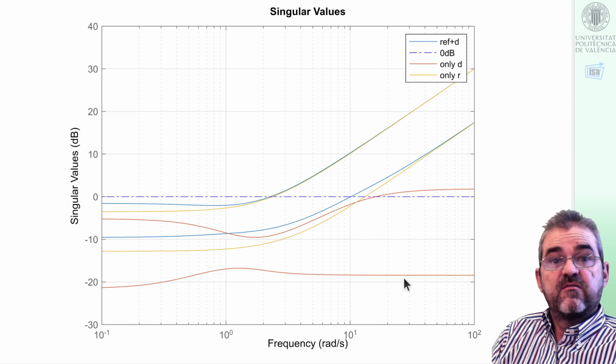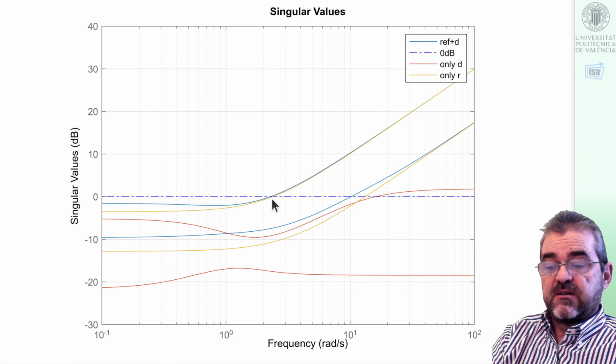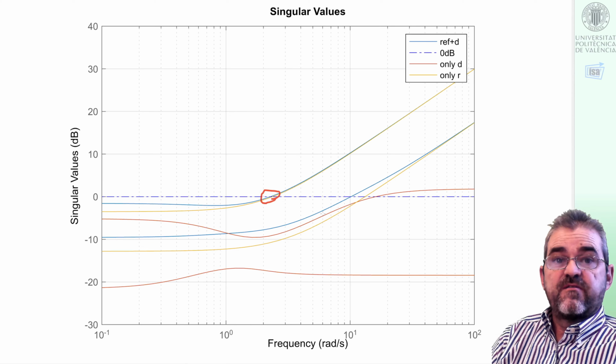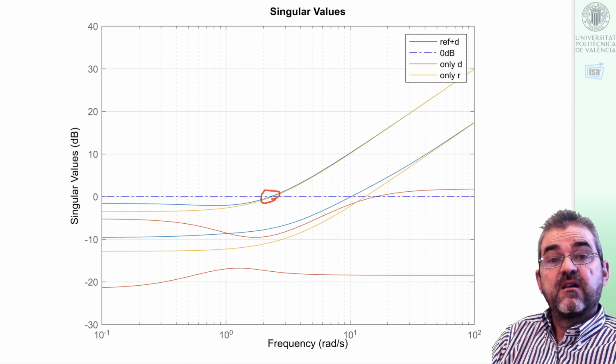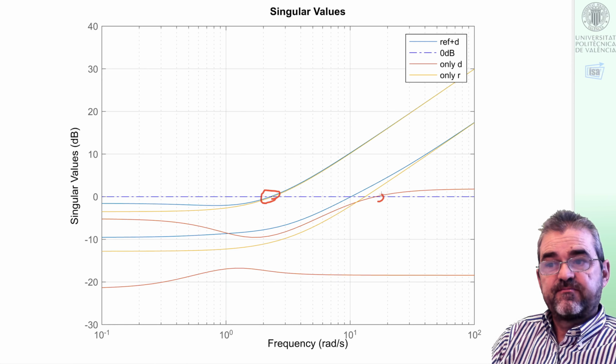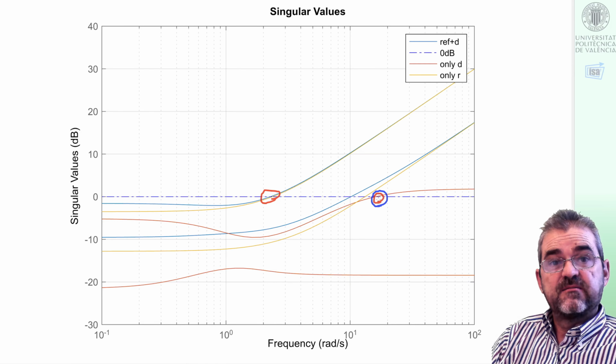So this is the final comparative analysis, and as we can see basically in here, the difference between set point tracking and set point plus disturbance is negligible. So it seems that the difficult thing limiting my closed loop control bandwidth is that I require too high a set point. Indeed, if I require just disturbance rejection, my bandwidth will be much higher.